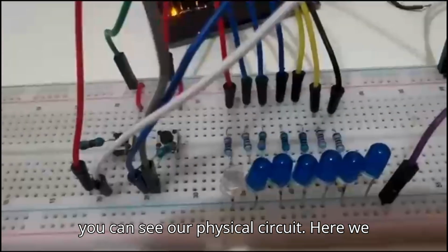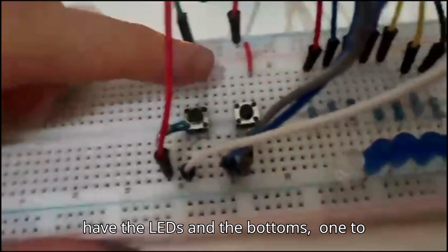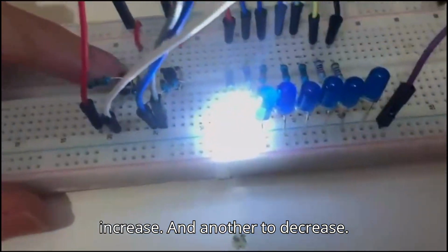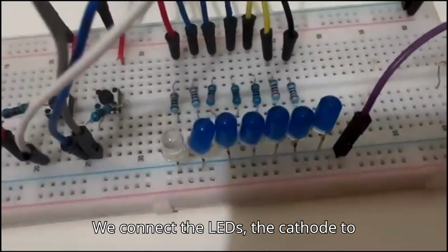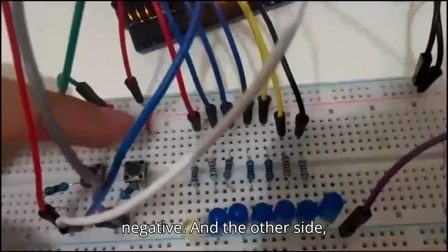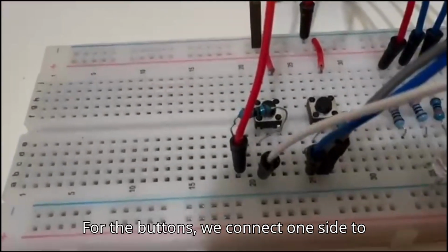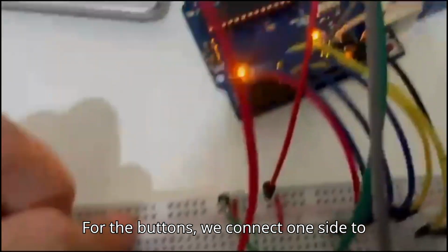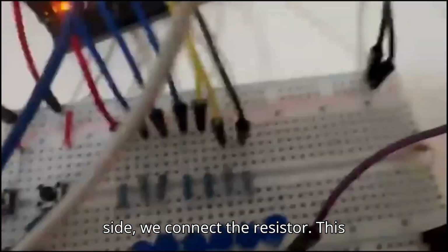Okay, here you can see our physical circuit. Here we have the LEDs and the buttons, one to increase and another to decrease. We connect the LEDs to the cathode to negative, and the other side to the resistor that goes from pin 0 to pin 6. For the buttons, we connect one side to negative, to ground, and on another side we connect the resistor.